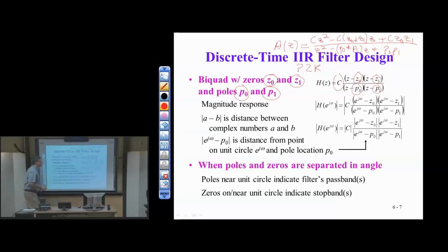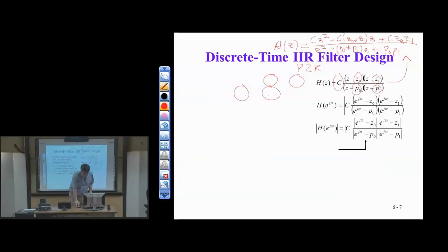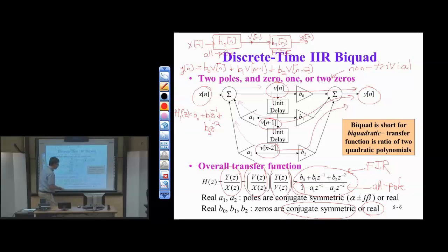So I've gone from the factored form in this pole-zero-gain representation, and multiplied out the factors to get the unfactored form, which is now more familiar. This is what we'd seen previously, although now I can divide through by Z squared and get what was familiar in the last slide, which is B0, B1, B2, and so forth. In the last slide, which we did in part 1, this was our transfer function. I have 3 feed-forward coefficients, B0, B1, B2. This is the FIR part. I have 2 feedback coefficients, A1 and A2. That's the all-pole part, the left-hand side of this biquad.